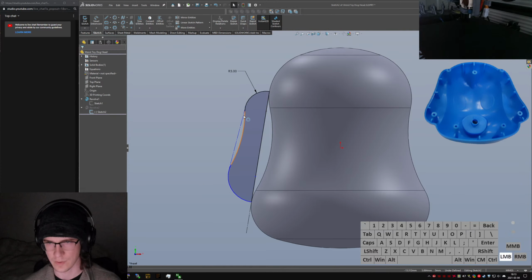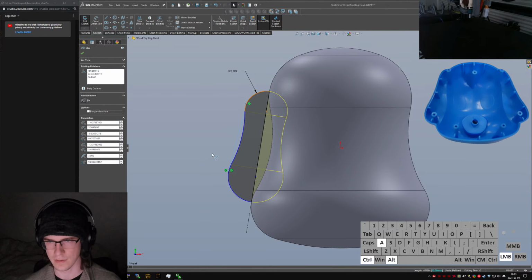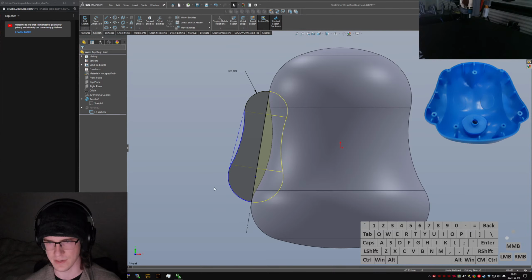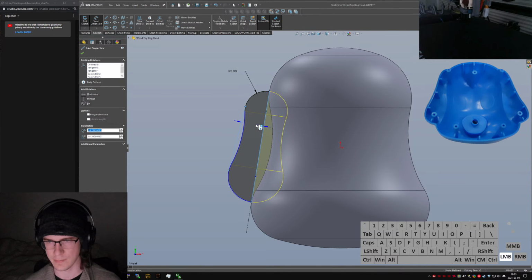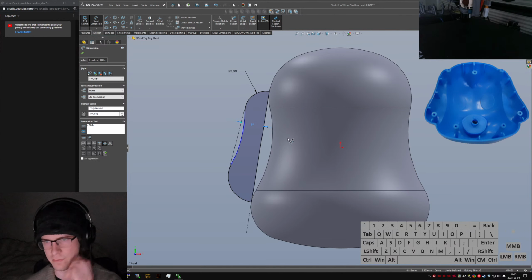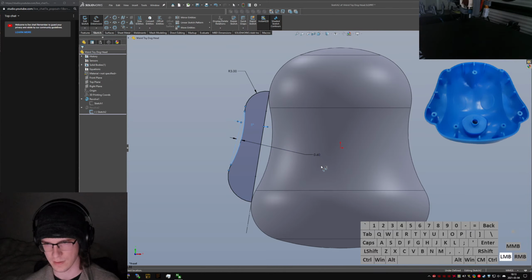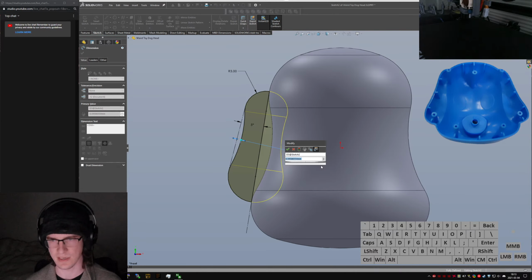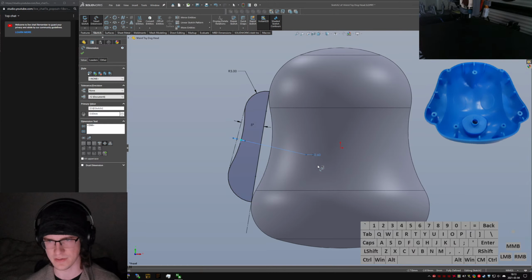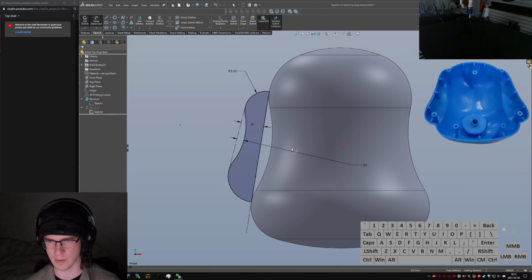Let's construction. What I'm going to do is I'm going to have this line out here be tangent to these two guys. Then I can keep my angular constraint for where I want that to be, which defines this radius, and then I can very quickly define how much I want as inset, which seems a little easier to define. Maybe even 1 millimeter. 0.6 is enough.